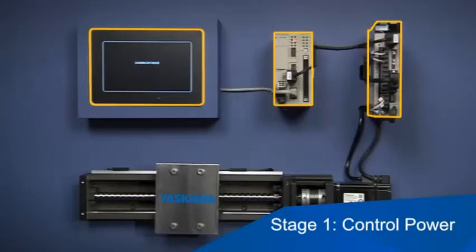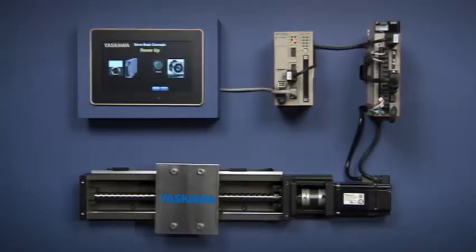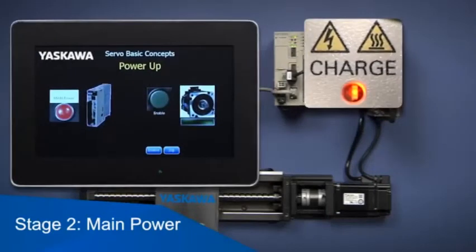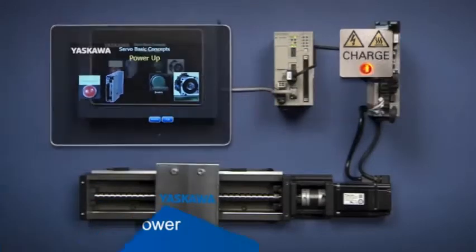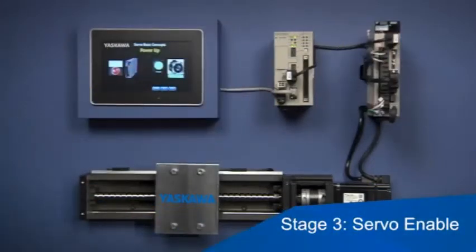The system is typically wired to power up the controller and the operator interface at the same time servo control power is established. The second stage is to apply the high voltage and high current power source that the amplifier will use to drive the motor. We refer to this as main power. The main power input allows flexibility in wiring to the servo amplifier. The third stage is to energize the servo motor. We refer to this as servo enable.